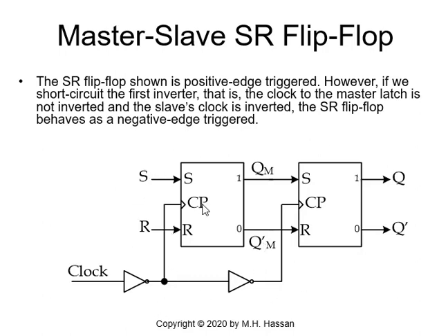Once we have the master-slave, it is a sophisticated circuit. It's more stable. It is either negative edge triggered or positive edge triggered. It is not level sensitive, and the stability we achieve from this flip-flop makes it much better than the normal latch.